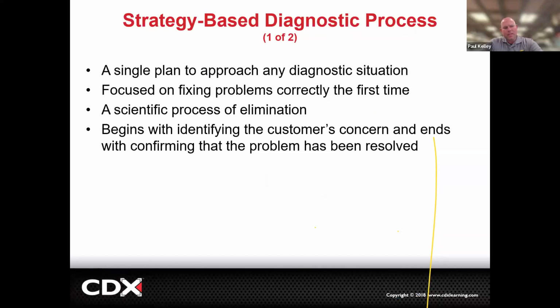And then kind of going more into strategy-based diagnosis here. You guys have covered this in a previous chapter, but this is where it gets a little bit more diagnosis related. When you go up to this car, typically the customer doesn't come in and say, "Hi, I would like you to repair the open circuit in my blower resistor." That's not likely. What's more likely is the customer is going to come in and say, "Hi, my AC doesn't work." And you're going to really have to come up with a plan to diagnose that concern.